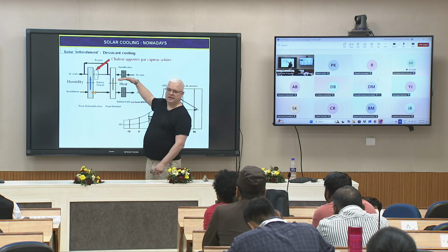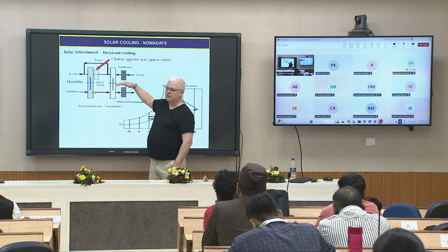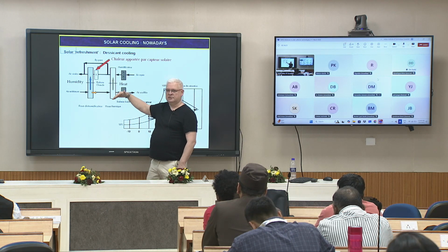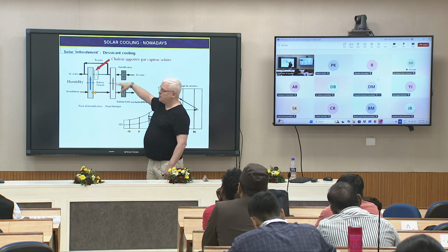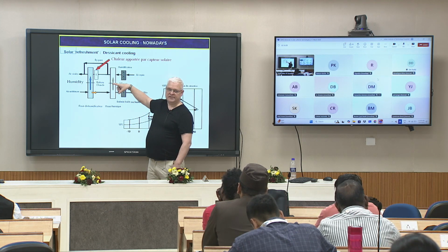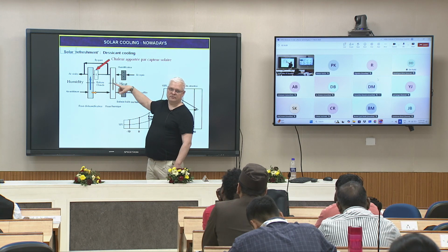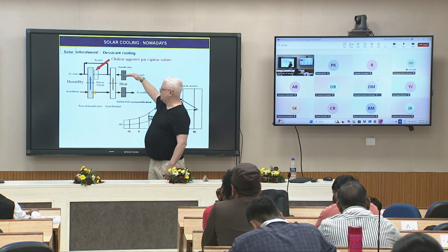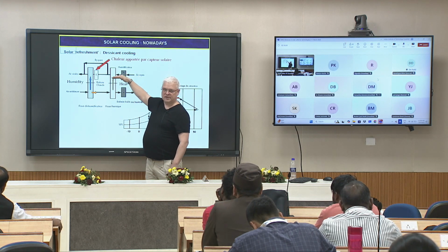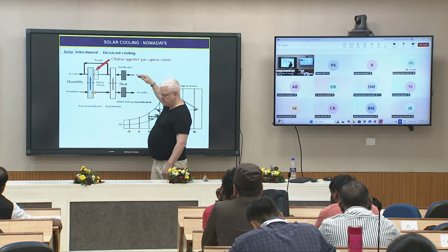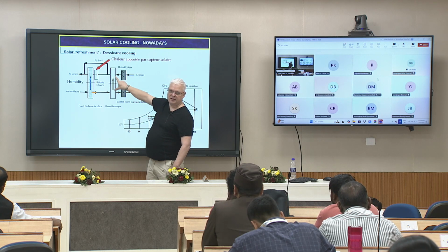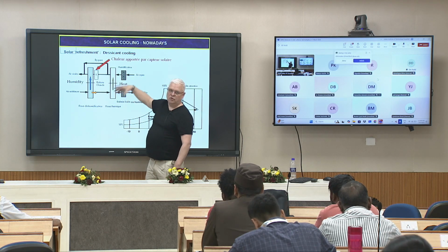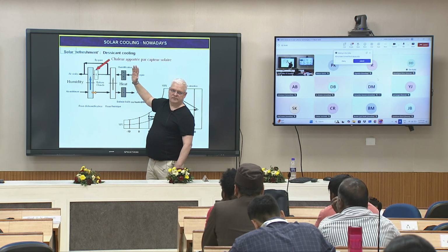We are using evaporative cooling here in order to decrease the temperature of the air before the heat exchanger. Like this, the heat exchange is better. The exhaust air is cooler, but we decrease it again in order to increase the delta T here, to allow to have more heat exchange.